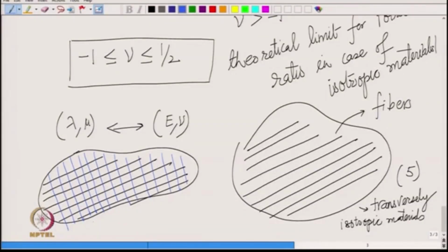Okay. So, these are orthotropic materials, and one interesting example is wood, and they have 9 independent material constants. You see the isotropic materials have 2 constants, transversely isotropic have 5, and the orthotropics have 9. And a more general anisotropic material will have 21 constants. Okay.